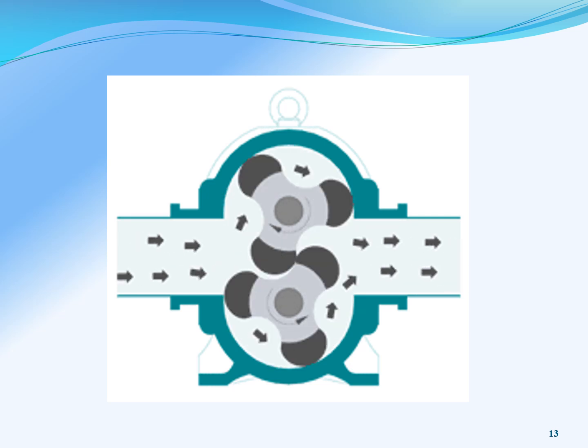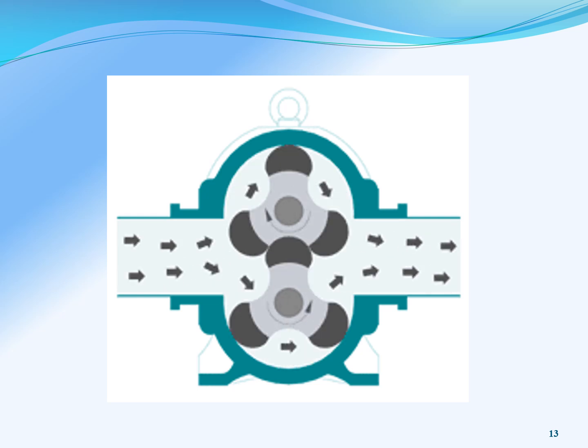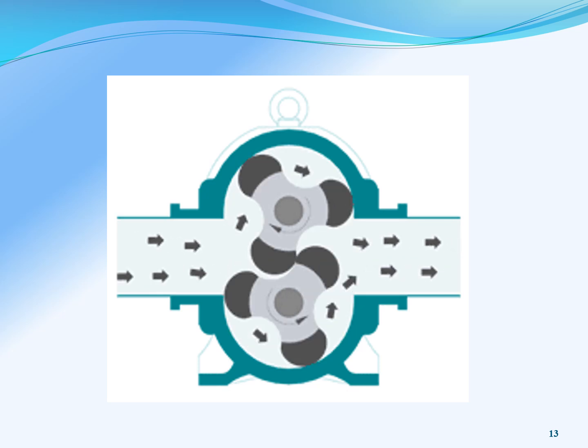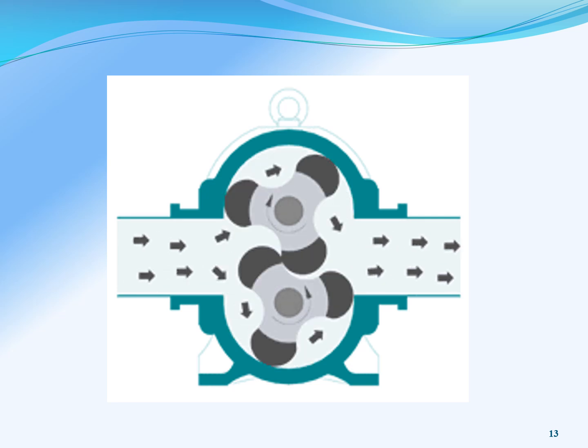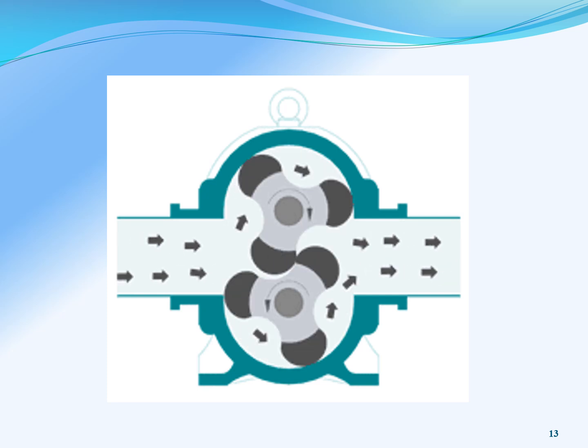So here you can see this is a lobe type rotary pump. As the water comes in, or the fluid, liquid, whatever you want to call it, gas, as it comes in, you can see that it's being forced to the outside of that pump casing before it's being distributed or displaced out into the system. Again, you can see how close those lobes are to the outside of that casing, right? So that's like those clearances that we were talking about earlier. Very tight, and that's why you can't have solids going through this type of pump.